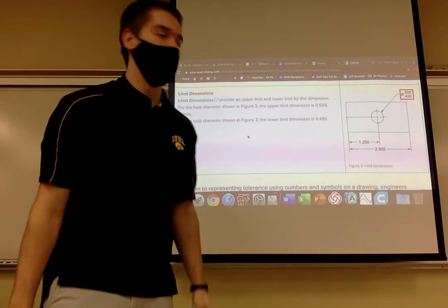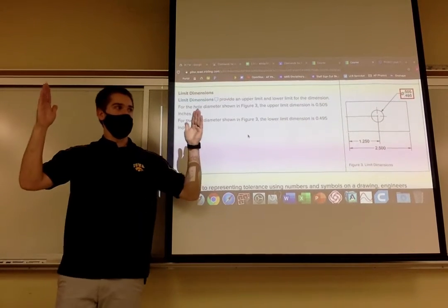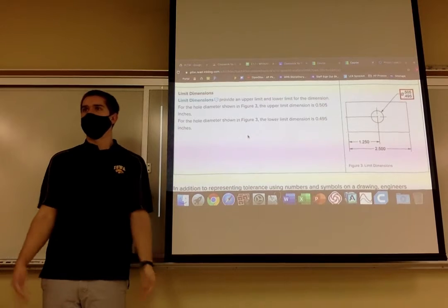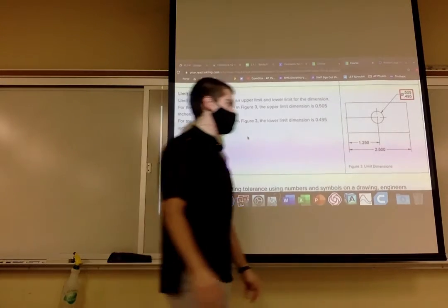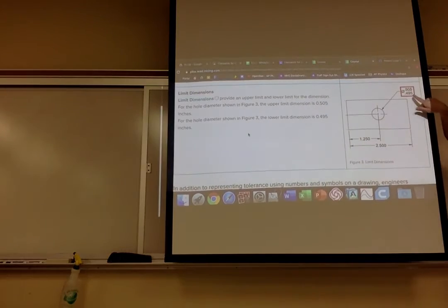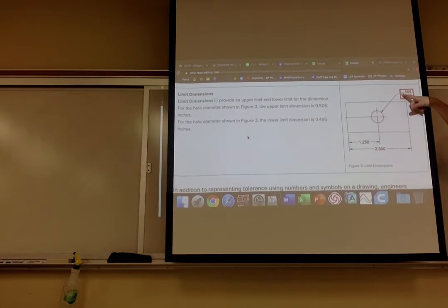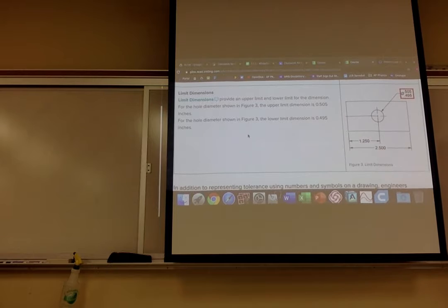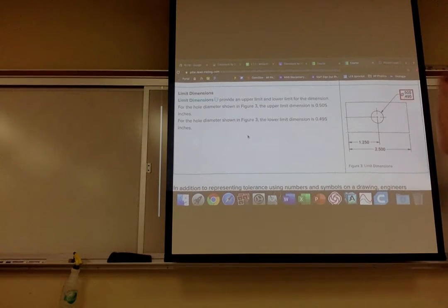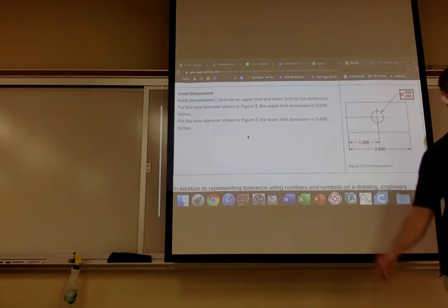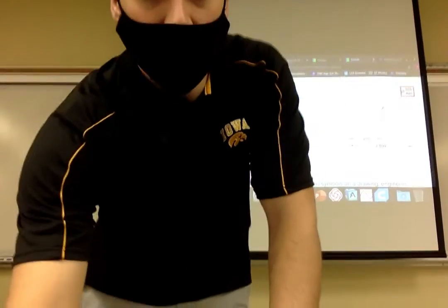The limit is something where you list the limits, right? A limit dimension means I don't really tell you what it should be. I'm not telling you it has to be half an inch. I'm just telling you as long as it's between here and here, I'm happy. That's what a limit dimension is. Here's my upper limit, here's my lower limit. As long as you're within there, I'm good. That's a third type of tolerance.